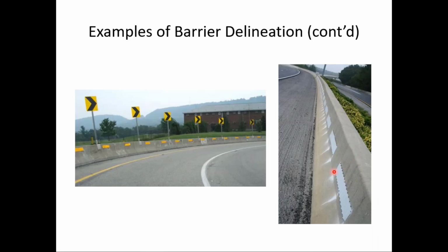Notice the lower right here. You may recall yesterday I think I showed this as an example of what was called a profiled pavement marking, and they work well on the pavement. The problem is they are not snowplow friendly because of the profiled nature, so they get damaged easily.